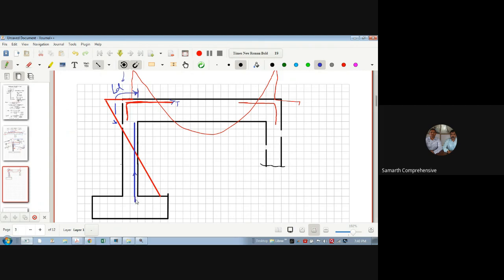So how will I develop this? From here to here. ऐसे करेंगे. And then here, right? There is a tension here also on this face, so I can provide that also. यहाँ से यहाँ तक. And how should I measure the development length? It should be measured from here to here. So this is my LT. Okay. To transfer the tension in this bar into the footing. Getting this? Yes, sir. So this way we can do that.